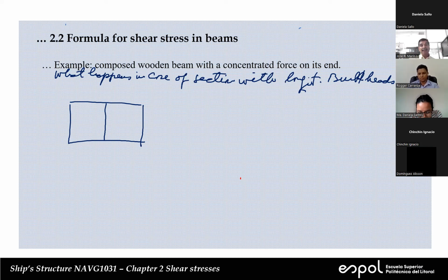Okay, you have a tank. Probably when you passed, you took the stability course. If you have a tank, right, you put liquid. If the ship rolls to one side, heels to one side, the liquid will move. So that will take the center of gravity and put it on one side. So it increases the inclination, right? So that's what we call the free surface effect. And that depends on the width of the tank, raised to the third power.